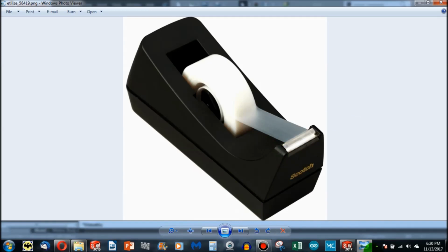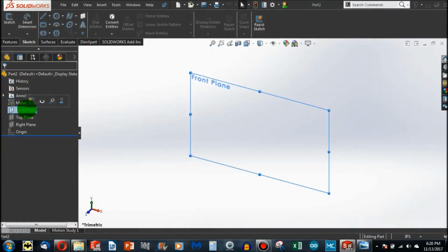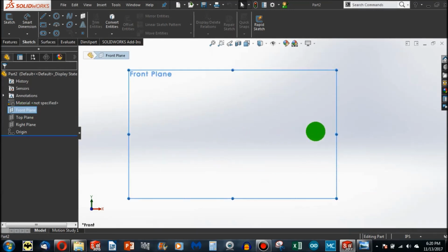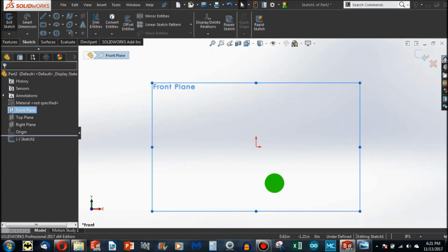of this side. So going to SolidWorks, I'll choose my front plane. And to get the front plane to face the screen like that, I just simply click on the front plane and press Ctrl 8. From there, with the front plane highlighted, I push the sketch button, and we're ready to start. The first thing is that I have these 9 options to sketch with.